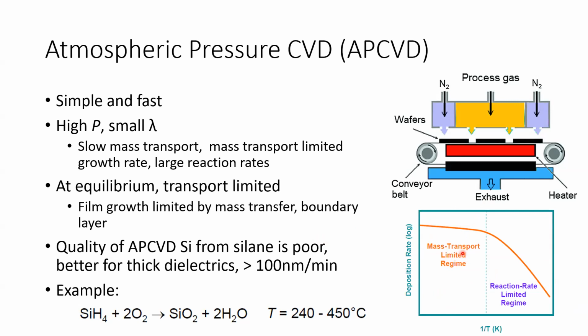And it has high temperature, large deposition rate. Because of this large deposition rate, it is usually used for thick dielectric deposition. So at equilibrium, it's transport limited. The mass transfer and also boundary layer dynamics will just control or limit the process.